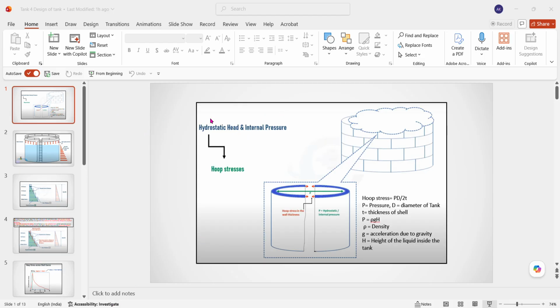Now when you calculate the thickness by the variable method, you see that in the market this chart is available for different thickness plates for different tank heights. It has millimeters and feet, and this is your diameter. If you calculate the diameter, thickness and height, you can calculate the stress value and then your thickness.